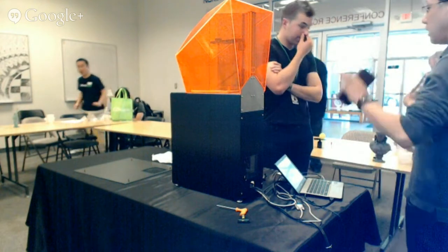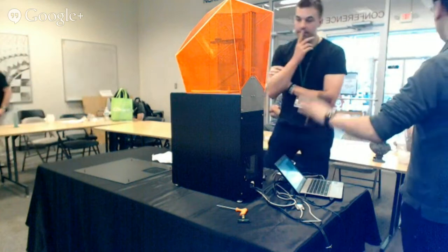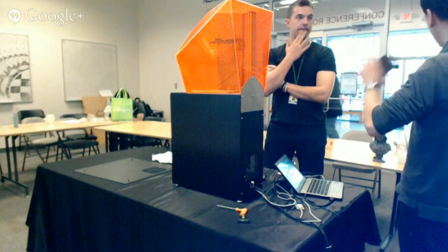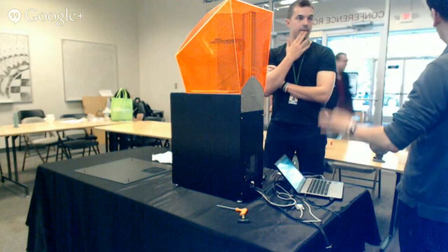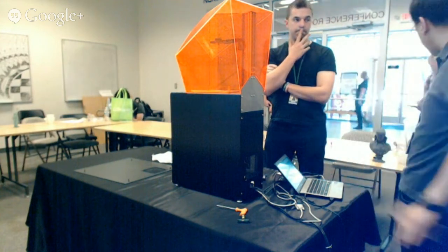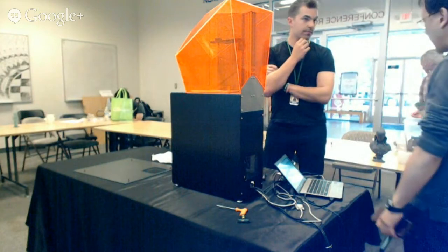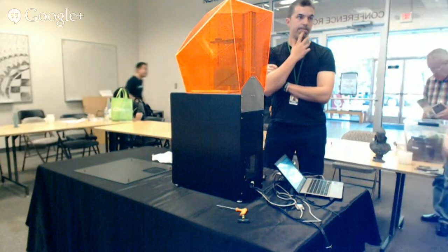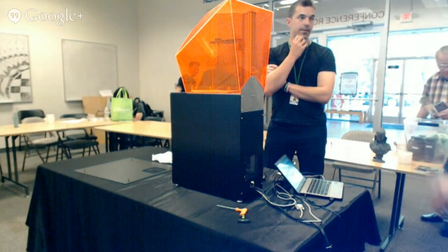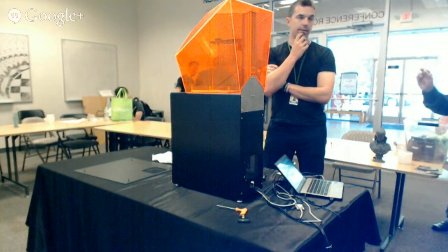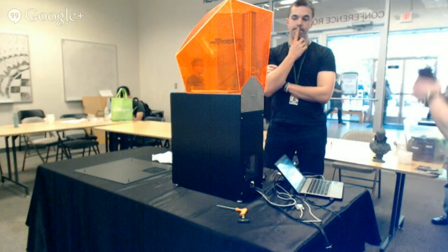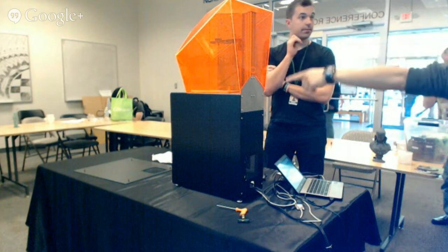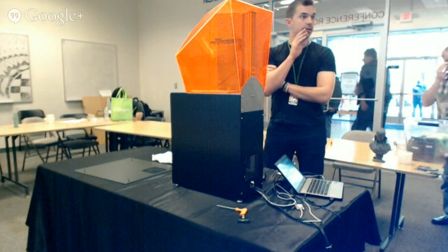In a pro printer, like a 3D Systems or an Objet, you always have to use the vendor's resin. And the vendor's resin is at least triple the cost of any of these resins. It's been specially made for that printer. So a lot of these variables, when we talk about shrinkage and other things, don't apply to the high-end printers. They control everything. They control the laser, they control the mechanics, they control the chemistry. The chemistry is matched to the laser and the optics, so all of that is integrated.